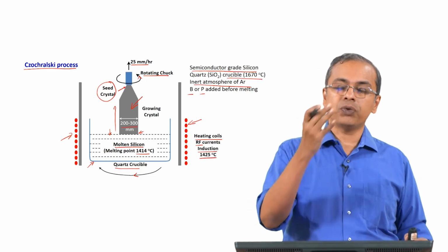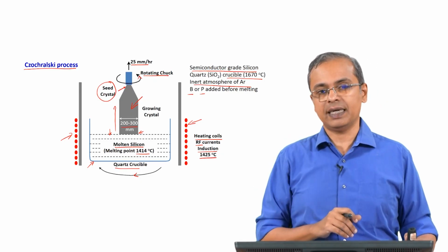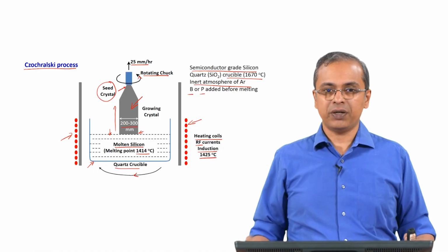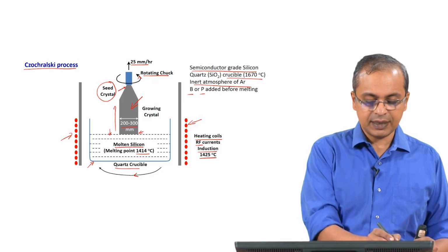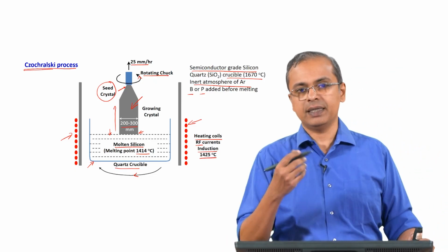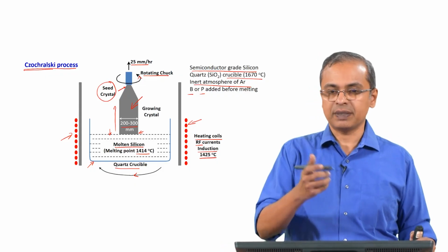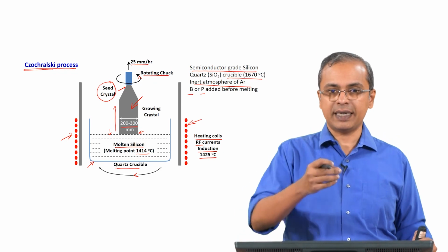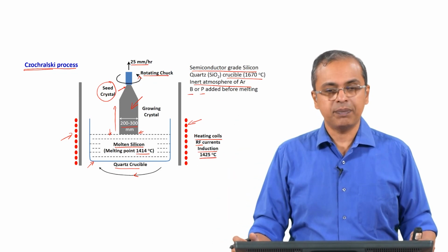In fact, that is the reason if you look at solar panels where they have used slices of the single crystal, you will see a circular cross section there. You do not see some random shape. So, anyway, that is the idea of the Czochralski process. Czochralski is the person credited with it. Apparently, he discovered it by accident, and he found that when he was working with some melt, he could pull out a single crystal by contacting it and then pulling something out which was cooling very well. So, that is the basic idea.